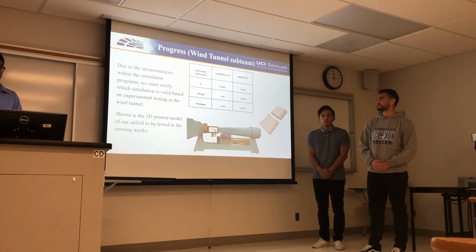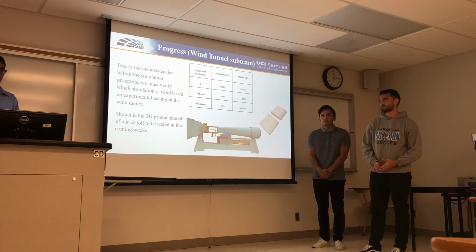Due to the inconsistencies of the simulations through SolidWorks and ANSYS, we need to verify them experimentally in the wind tunnel, and we are going to do that by printing various 3D models of the airfoil with varying angles of attack.